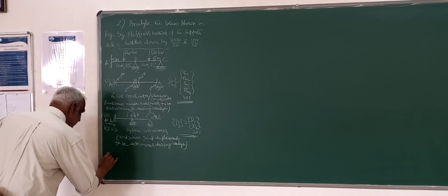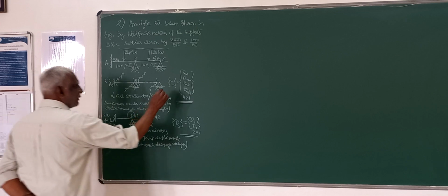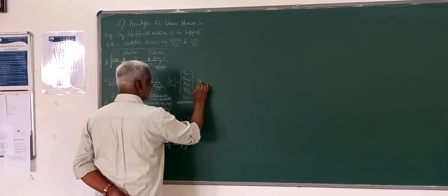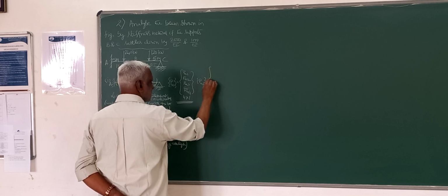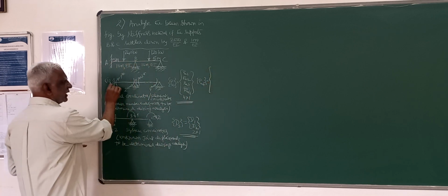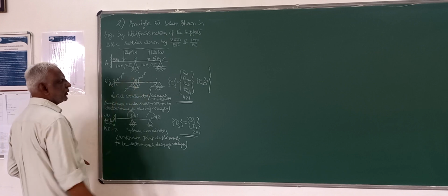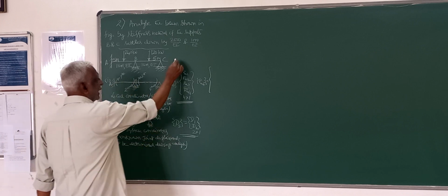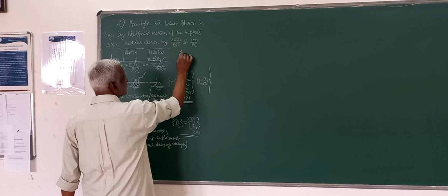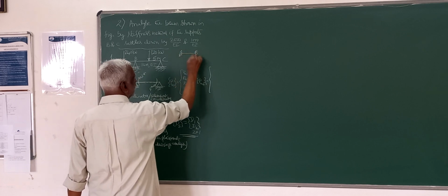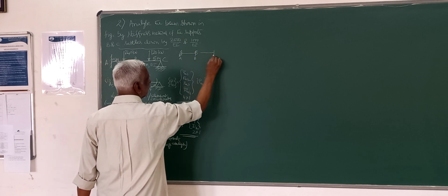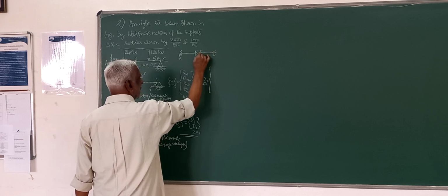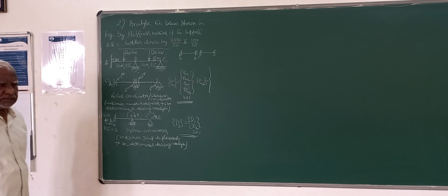And of course, here we can evaluate what is known as the fixed end forces of the members also. So you can assume each member to be fixed at the ends like this. Whatever the member is, we have to assume it to be fixed at the ends, not allowing any displacement.